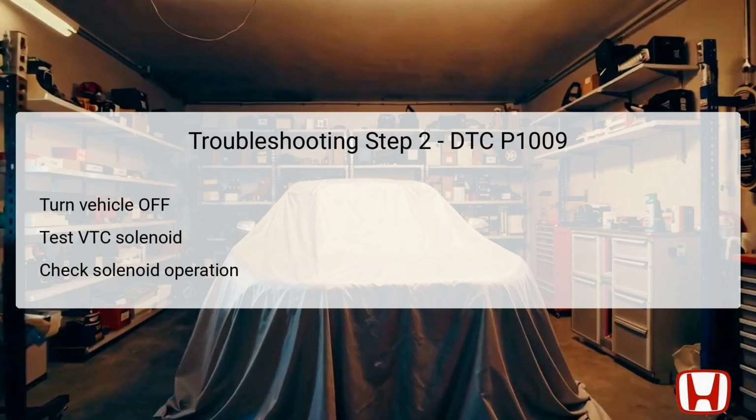If the solenoid valve functions correctly, it suggests that the problem may lie elsewhere in the VTC system. However, if the solenoid valve is found to be malfunctioning or faulty, it must be replaced to resolve the DTC P1009 issue. This is crucial, as the solenoid's function directly affects the actuator's ability to adjust timing, which can lead to performance issues when compromised.